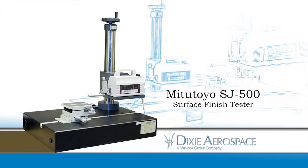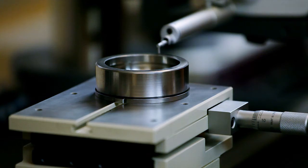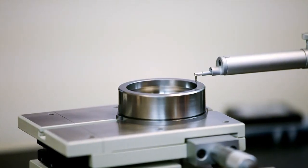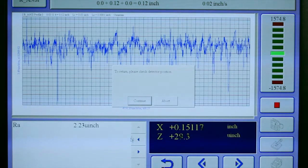The Mitutoyo SJ500 Surface Finish Tester is utilized to collect all surface finishes. This machine supports 43 types of analysis parameters, complying with surface roughness specified by ISO and JIS standards. Some of the common contour analyses performed by this machine include area, circle, angle, coordinate difference, step, and inclination.